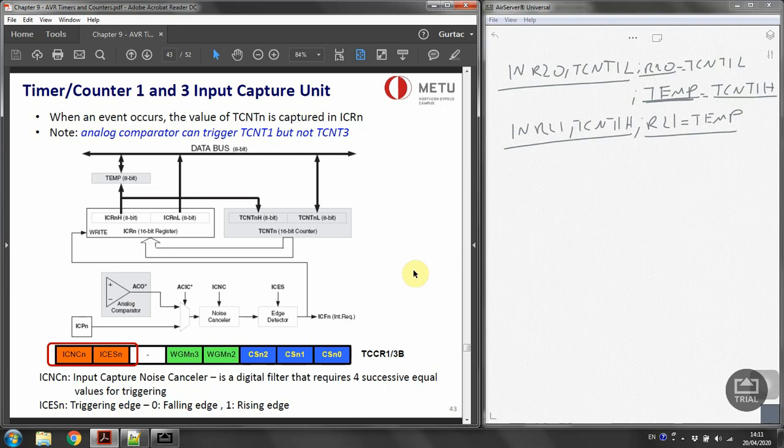And before we give that example, I just want to emphasize something like we have done with timer 0 and timer 2 in the normal mode operation. You do remember we have got this timing. So over here in the normal mode we have got a 16-bit value in TCNT. So what is actually happening over time?